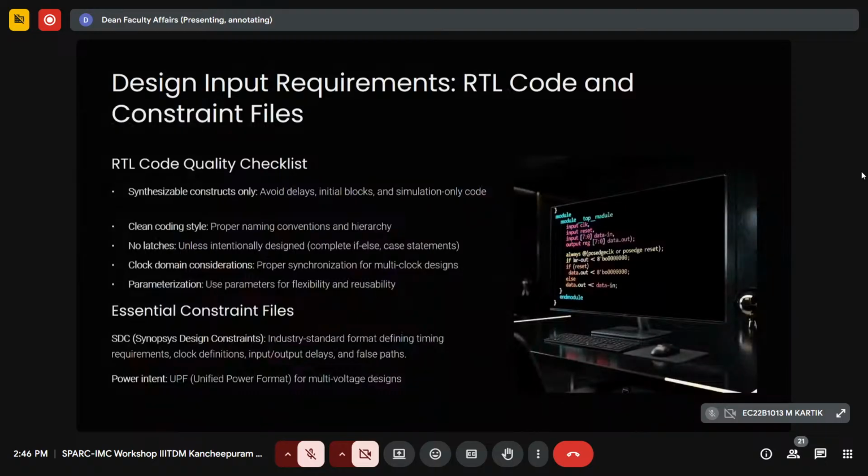If you take a latch, the latch is level sensitive, so data can be launched wherever the level starts and captured at any point in the level. The level is so big. For example, with a clock period of 0, 5, 10, from 0 to 5 the data can be launched, but anywhere between 10 to 15 the data can be captured in the latch. An edge is a single point, whereas the latch is basically half of your timing cycle.